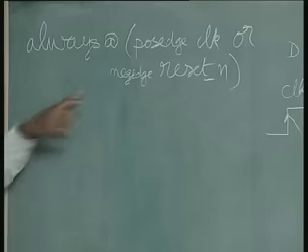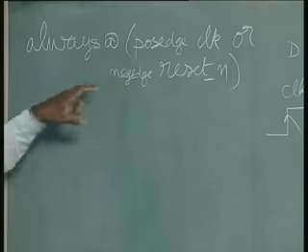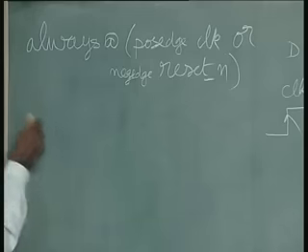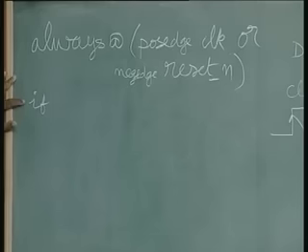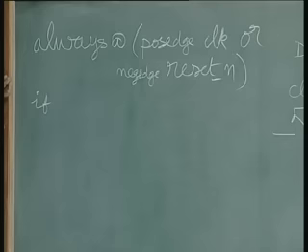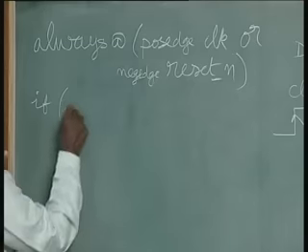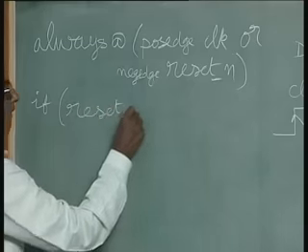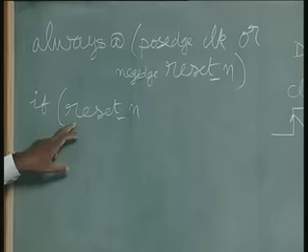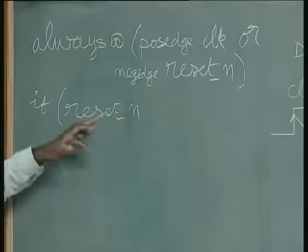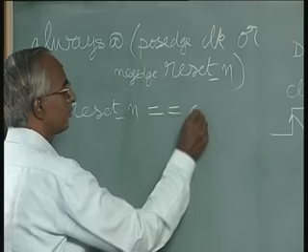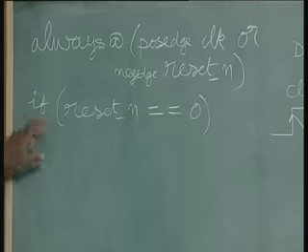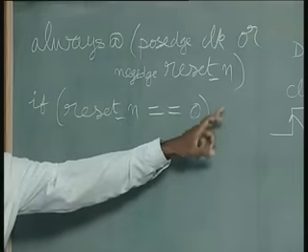And now coming to this, we have already accounted for negative edge of reset, but when we write for reset, how do we write? We use a new term called if statement. This is similar to the if else you have used in C. If you use if here, what you can do is just take this reset underscore n, and we are going to see whether it is high or low. So in this case it is active low, so we have to check for 0 as such. Notice that after if there is no semicolon, this is a very important thing.